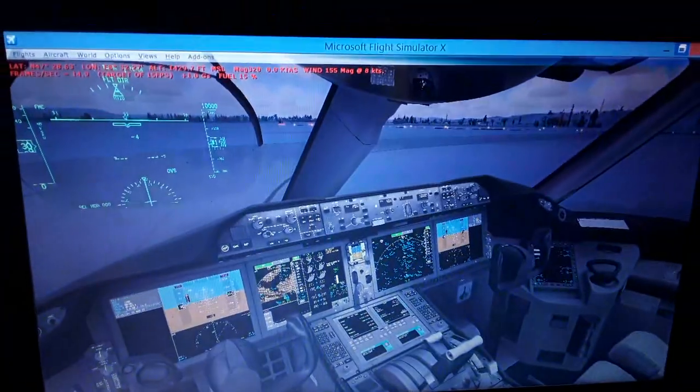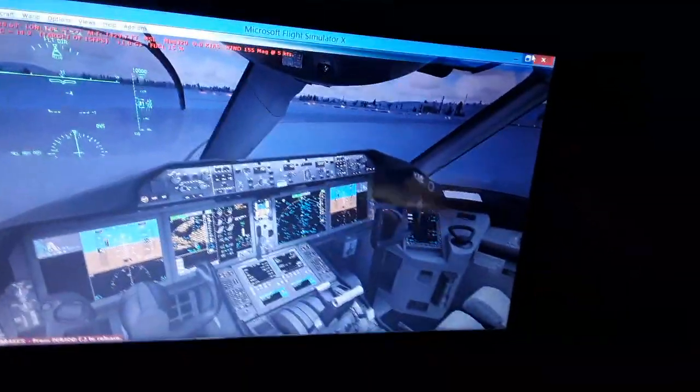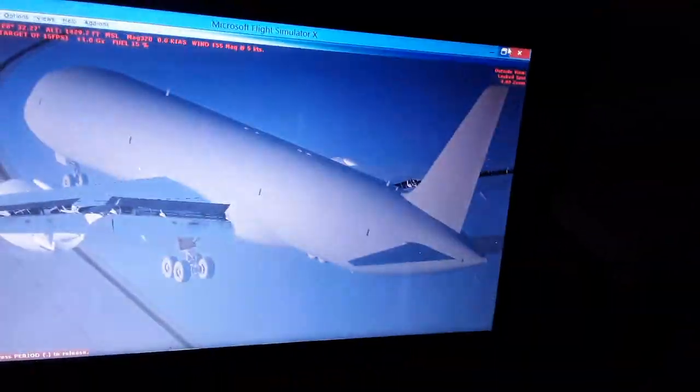We're going to have 25 to 30 degrees of flaps for approach, the landing gear extended down, a pitch attitude of about 9 degrees or less, and also an airspeed of 160 to 170 knots, or about 270 to 300 kilometers an hour. So we're going to see the approach and landing, the full flight, and also the full flight plan. I'm going to show you now how to create the flight plan here using the flight management computer.